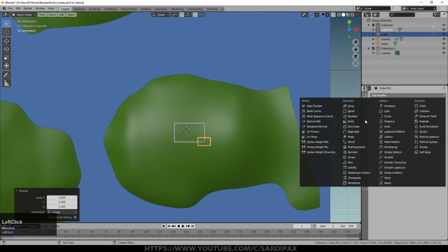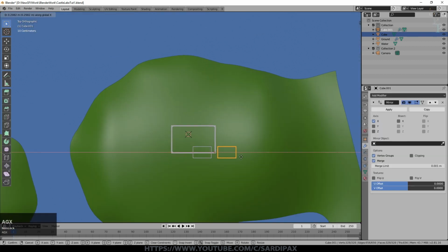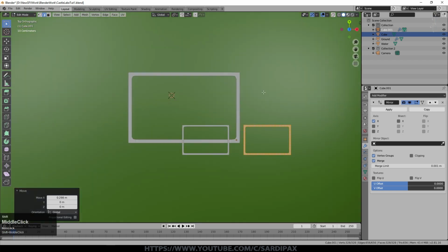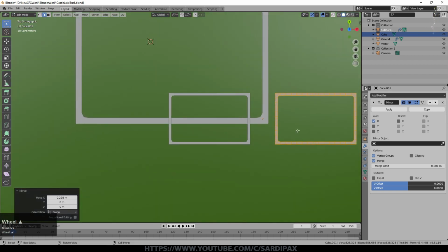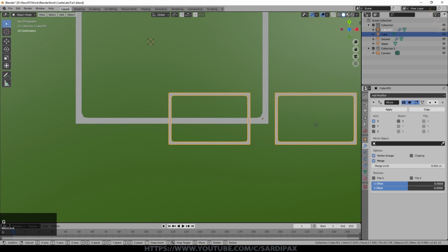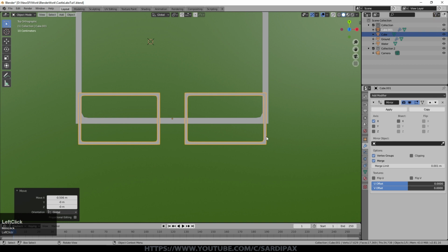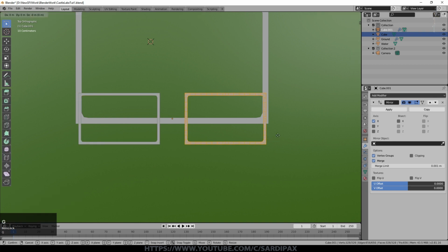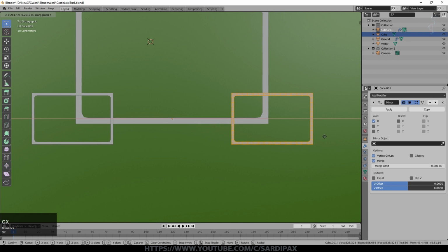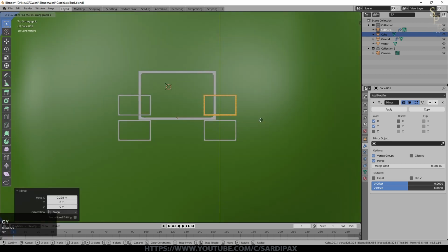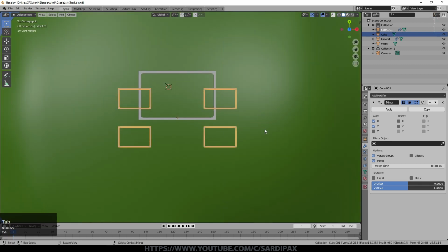And we can mirror that. I've gone into edit mode and I'm just moving it on the X-axis. I'm just going to put that center point. As I said, you can do this before you apply the mirror modifier, and then you won't need to do this separately. Back in edit mode, and I'm just moving this around, and now moving it around on the Y-axis as well.